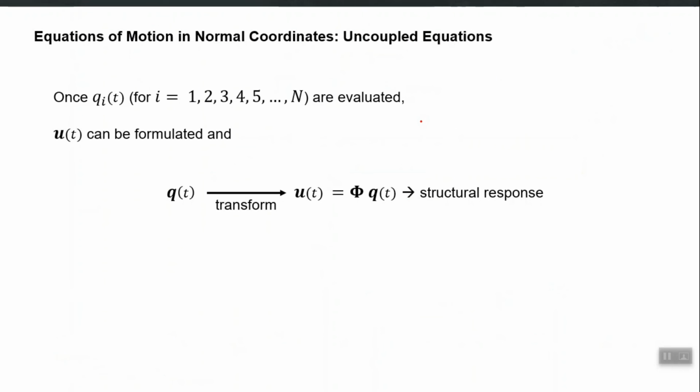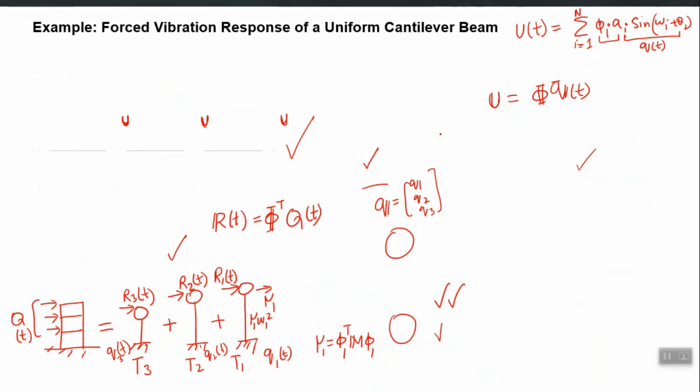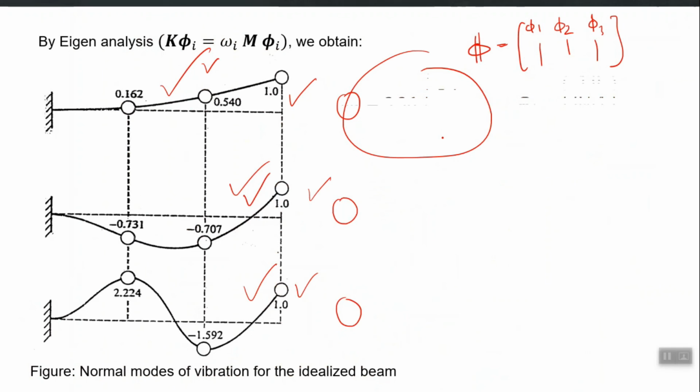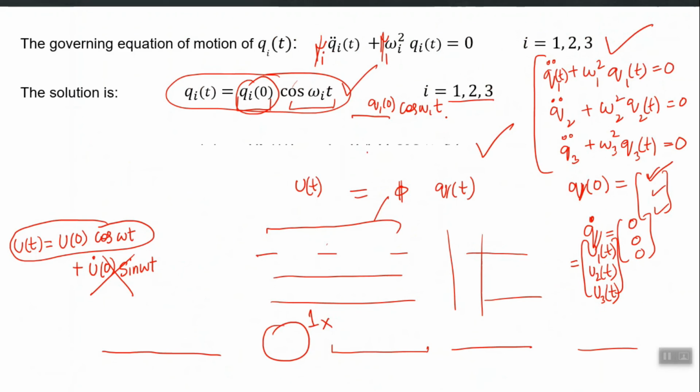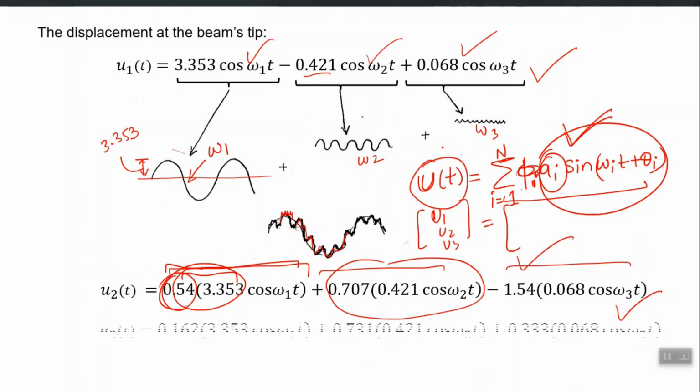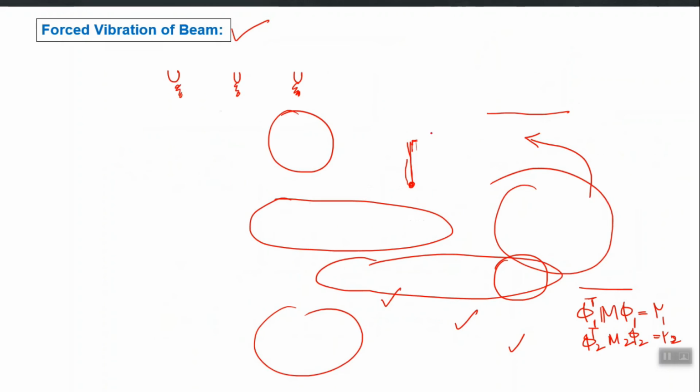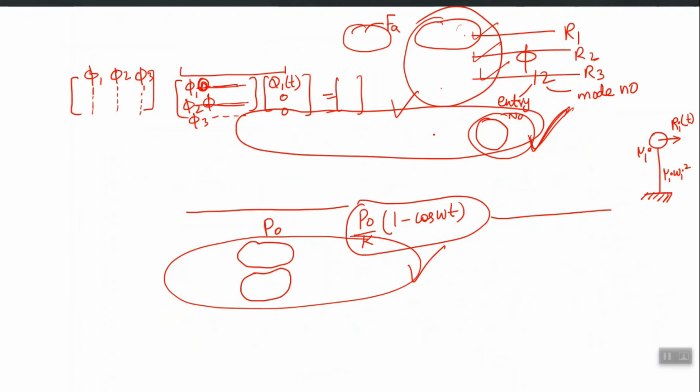If the damping matrix follows this condition, we call it classical damping, and if it doesn't follow that condition, we call it non-classical damping. So it means that in order for modal RHA to work, we should always have classical damping, right? Otherwise this uncoupling may not be possible, and therefore the modal RHA method itself will not be possible.